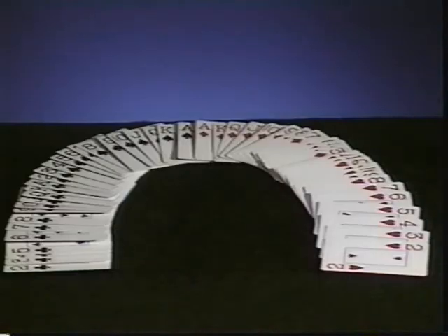In some situations, you can eliminate possibilities faster through a troubleshooting technique called half-splitting. With this method, each time you check a part of the process, you reduce the remaining number of possible causes by half. We'll use a deck of cards to explain the half-splitting method.